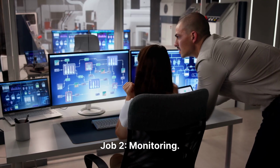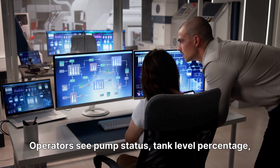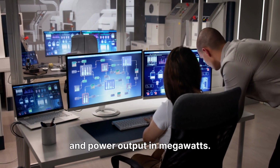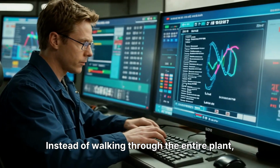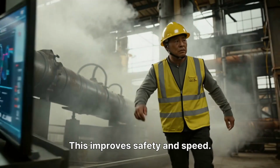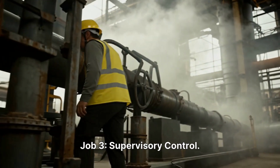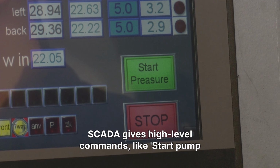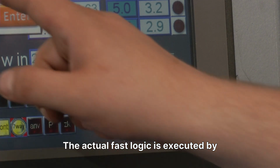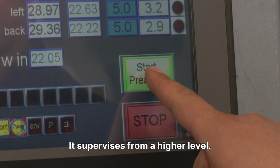Job 2. Monitoring. SCADA displays live conditions on HMI screens. Operators see pump status, tank level percentage, and power output in megawatts. Instead of walking through the entire plant, an operator views the process from one room. This improves safety and speed. Job 3. Supervisory control. SCADA gives high-level commands like start pump 2 or change pressure set point. The actual fast logic is executed by field controllers. It supervises from a higher level.